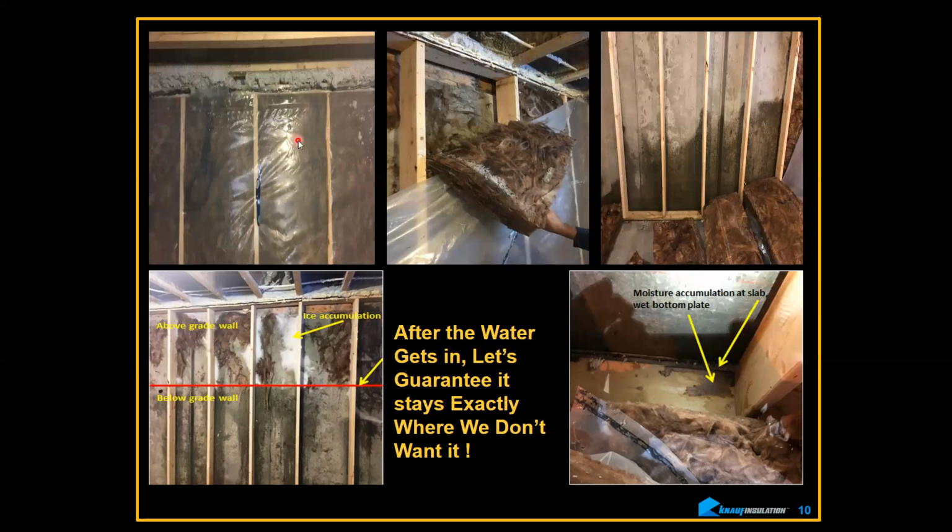So now you have an impermeable layer that you put staples in to hold it together. So every staple has 2 holes. Every time you have a stud, you're going to have 20 or 30 staples in it across this entire building. And then you're going to cover it with drywall and put another 30 or 40 holes per sheet in it. So what happens is there's enough moisture from the interior that gets driven in the wintertime because everything goes from more to less, and it's warm inside and cold outside. It's going to drive the moisture through the drywall, which is highly permeable and very absorbent. And what's going to happen is there's going to be enough pressure to get it through those holes, but not enough pressure to bring it back out to dry to the inside. And that's the reason all these things fail.